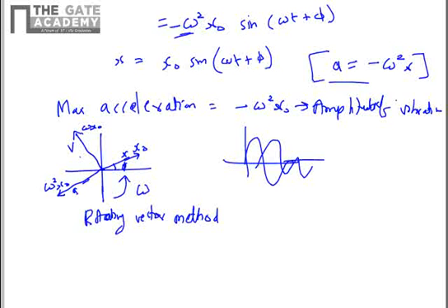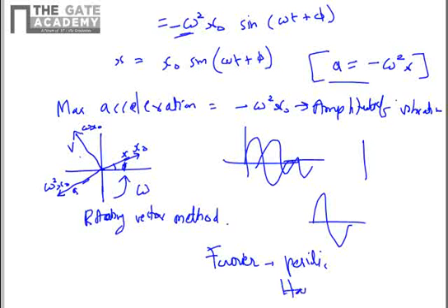So by decomposing the vibration into vectors, it is much easier to handle those, and you can handle addition, subtraction, what kind of superimposition you want to do for the vibrations. This same property allows us to decompose a very complicated vibration into simple harmonic components, because from the Fourier series you know that any periodic motion can be decomposed into harmonic motion.